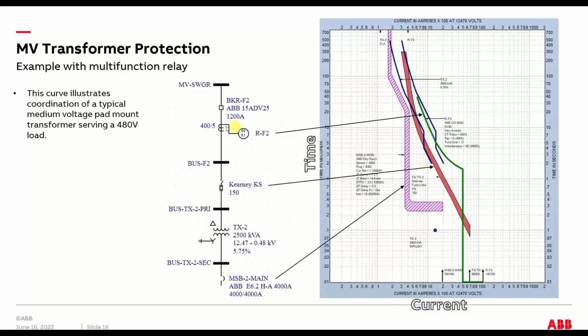Here's just a real quick example showing this whole system put together with a relay combined with low voltage breakers. So you have a transformer in between. So you've got your low voltage breaker, transformer, fuse protection. It's pretty typical, and then maybe an upstream relay. So this shows a good coordination between your low voltage breaker, fuse, and upstream distribution feeder relay, and this includes all the required time delays plus safety factor to allow everything to be fully coordinated.